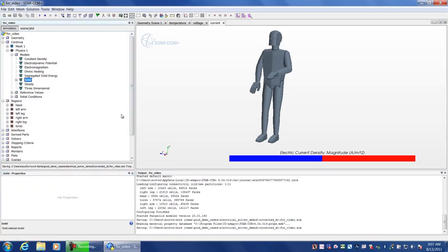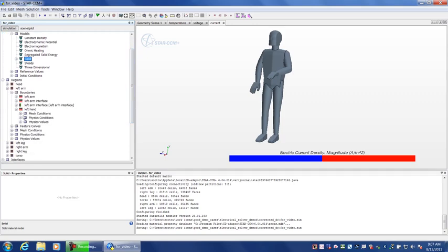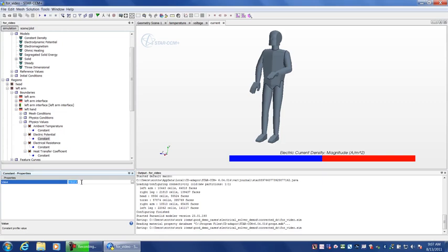Now it becomes time to set up our boundary conditions. There are only two boundary conditions that really become an issue here. We're going to simulate that our human here has used his left hand and touched something he shouldn't have, let's say a live wire. So we're going to change the physics values here. Ambient temperature is going to be constant. Electrical potential we've set here as 110 volts, which is a typical United States source. The electrical resistance we're going to say is none at the source, and the heat transfer coefficient, again looked up from the internet, for a human being is about 2.68 watts per meter squared Kelvin.